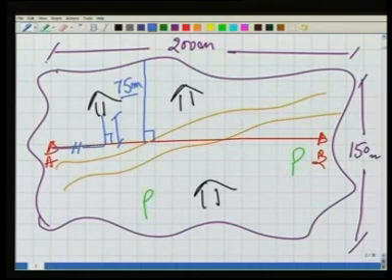While you are working with the tape, how do we make the offsets in the field? We have to erect the perpendicular or the oblique offsets, and we swing the tape in order to make it perpendicular. If you swing your tape, which is 75 meter long, can you think of it? It's not possible.